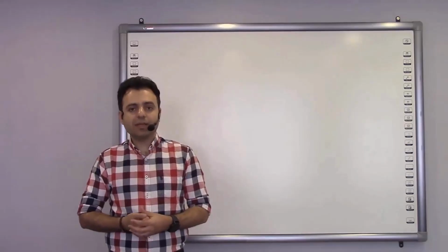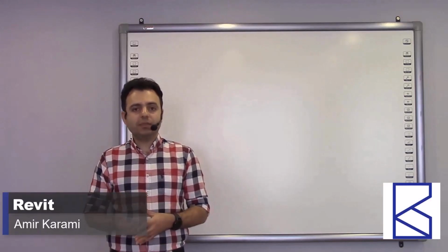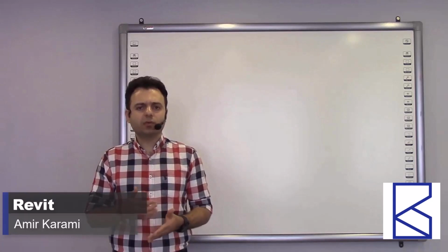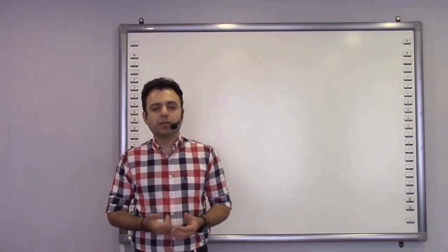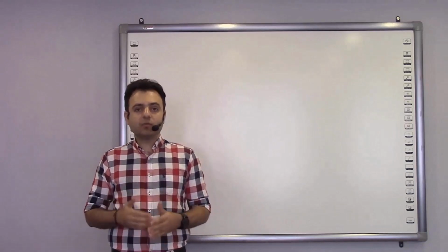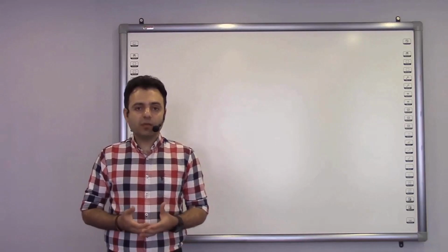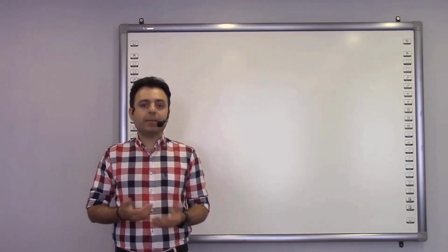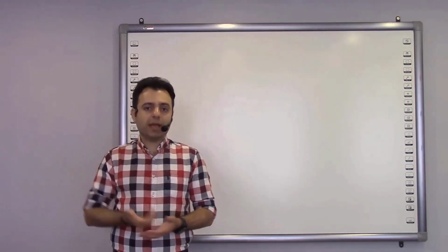Until this part of our lesson, we have talked about the way of drawing the walls. And just like I told you in the last part, with the commands in modify like trim, extend and offset and any other, we could draw interior walls of a project, but we didn't talk about the height. Now I want to talk about the height management or the floor management and specify the floors of a project.